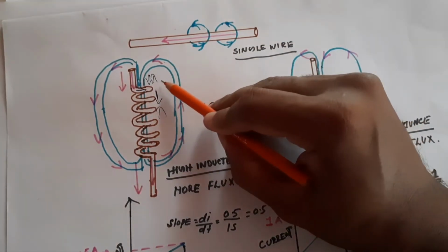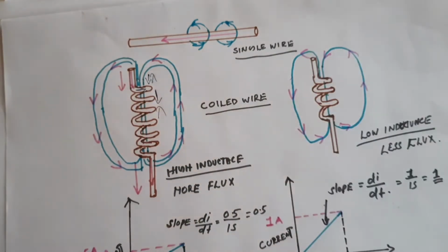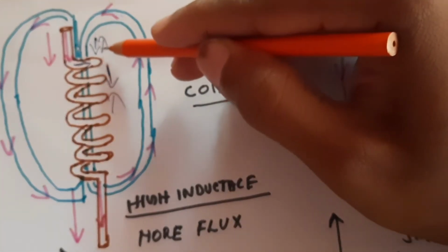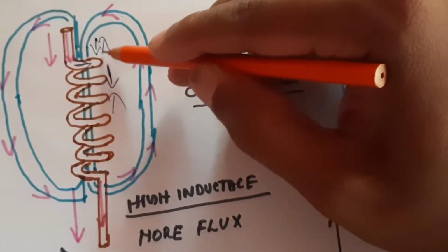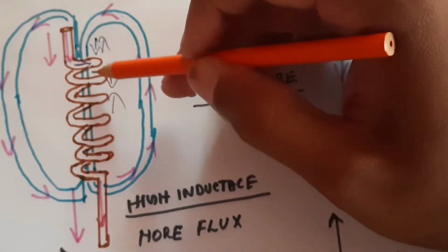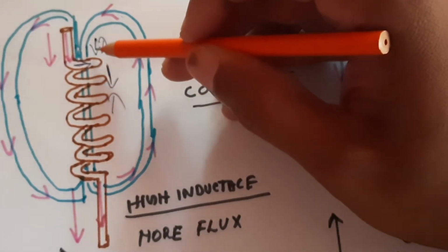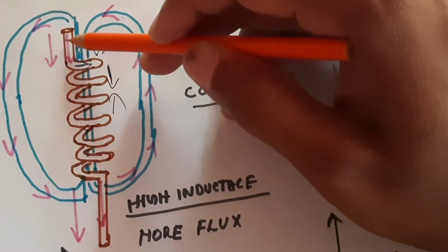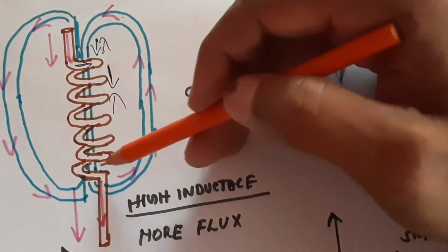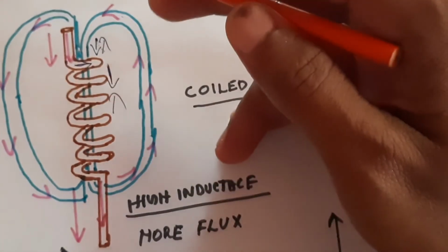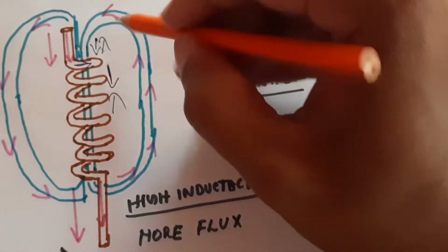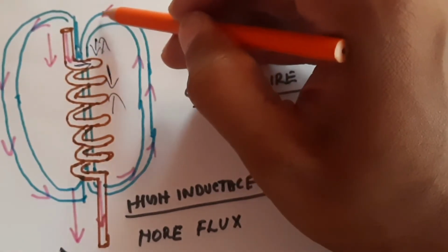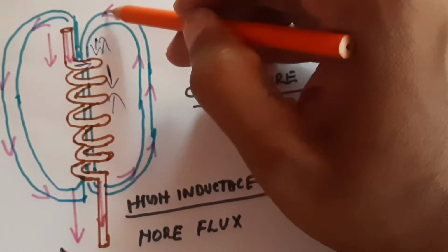If this happens, what will be the result? One is coming in and the other is coming out, so the two fluxes cancel each other and no inductance is left. The input voltage then sees no inductance, and heavy current flows through it and will damage the coil. So the direction of the lines of flux I drew was a mistake. It should be only in one direction.